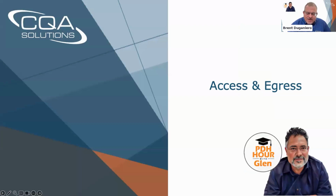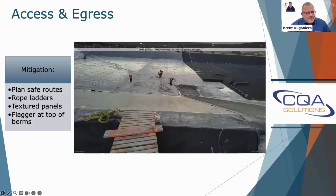Access and egress. How are we going to get into and out of our work area? Well, we already talked about that bridge. But we might have other ways that we need to get into our site. So we've crossed our anchor trench, but what if we have smooth liner? How are we going to safely get up and down to the bottom?